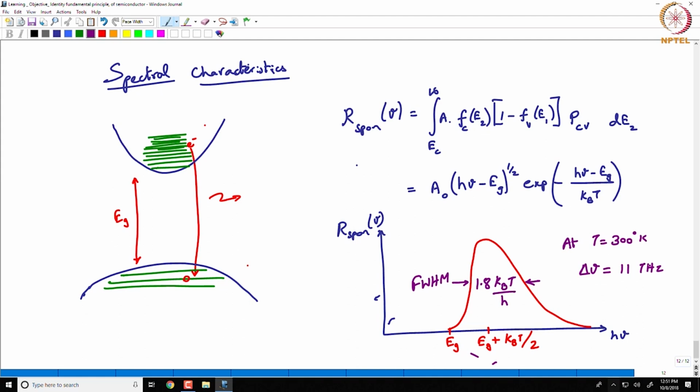And how are we getting white light which is spanning 400 to 700 nanometers? It's because each of those LED elements has a phosphor coating on it. That phosphor coating gets illuminated by UV light, just very much like your old fluorescent lamps. You will have a phosphor coating on the inside, so you will emit white light.